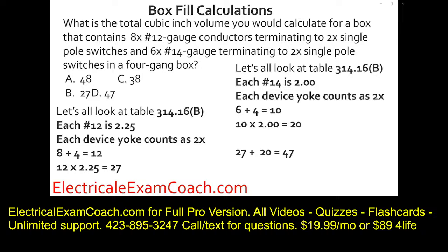We have our 6 original conductors, and we have 4 more based off of our count, because remember, it's based off the largest wire that terminates to that device. We bear that math out, total the two together, and end up with 47 cubic inches. Let's get to it.